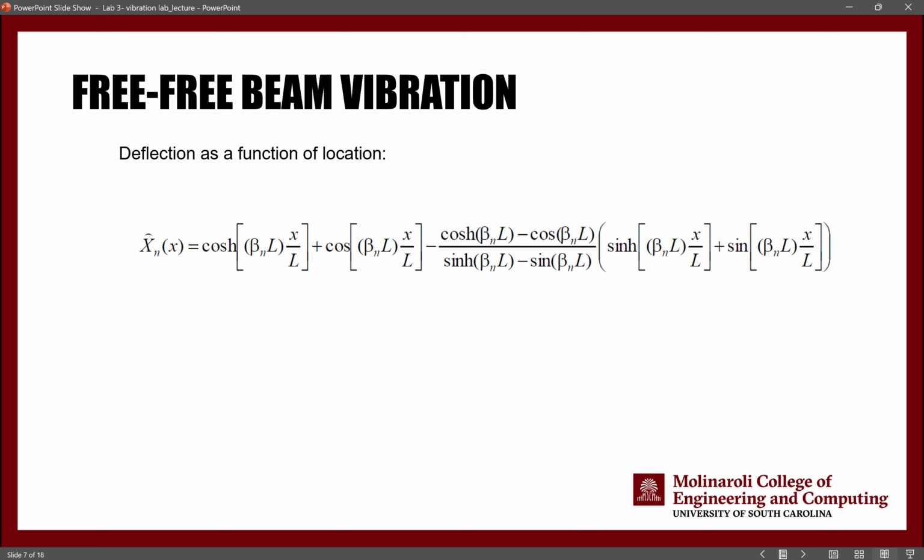Okay, and the general equation for the vertical displacement, see, this is x of n, the displacement normal to the beam. So this is essentially the amplitude of your vibration, as a function of the location on the beam and all of these other parameters. Again, the idea is at node positions, this normalized value is going to be 0.